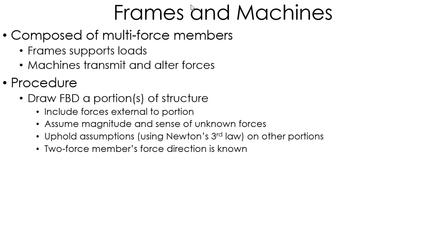Now, when you start breaking this apart, there's internal loads, interactions between members that I have to take into account. We'll show you how to do that in the example. So you want to include any external forces to the portion that you're looking at. If you've got any unknown forces, of course, you just assume their sense and the magnitude of them. But what you're going to want to remember is to keep with that assumption. If you make an assumption, stick with it.